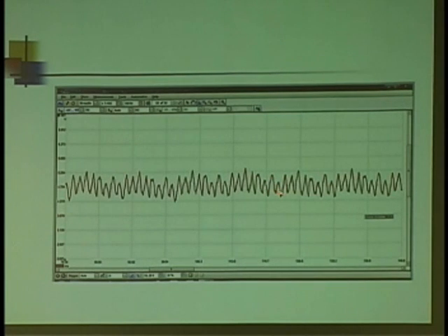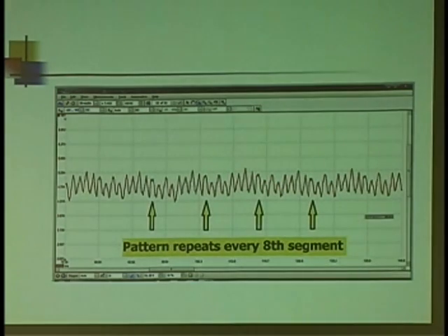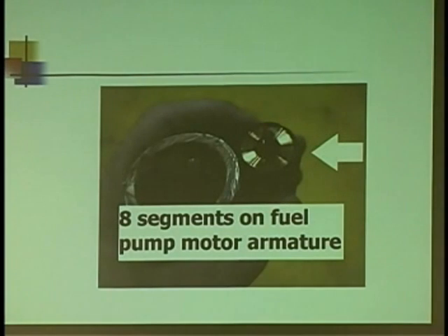Since I have a repetition identified, I can use that to divide it up. Every 8th segment, that pattern repeats itself. Well, that kind of fits in because that particular fuel pump has 8 segments on this motor.